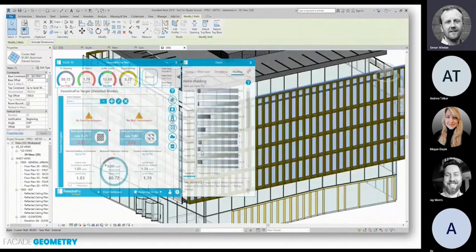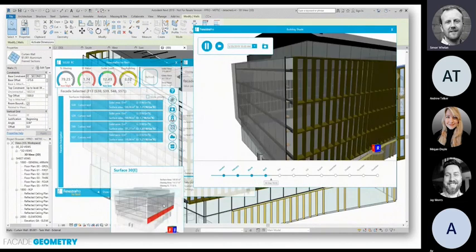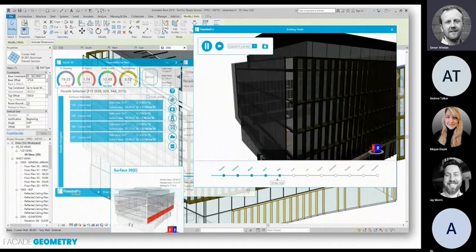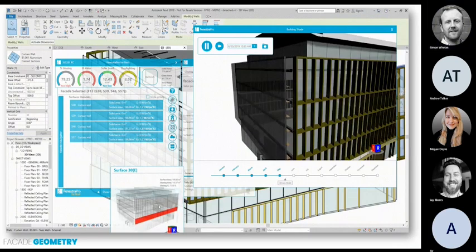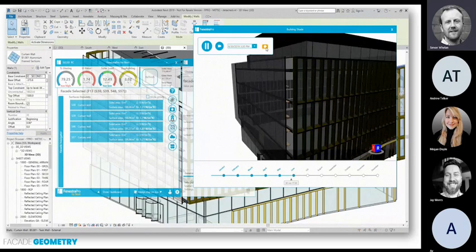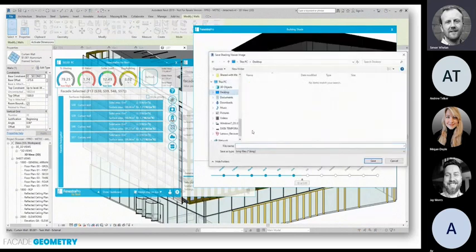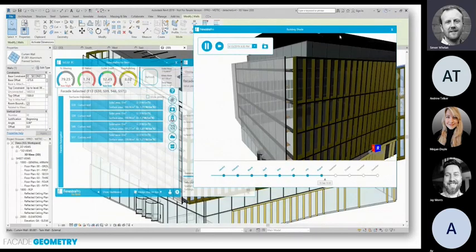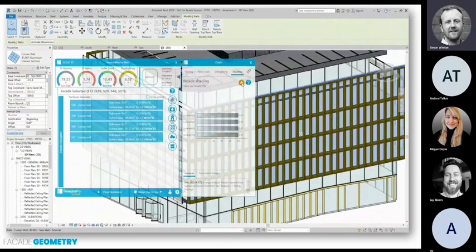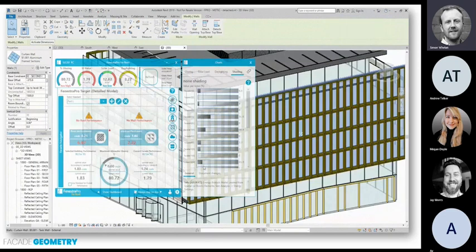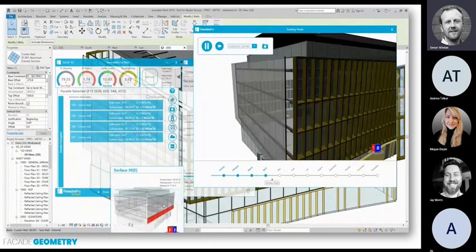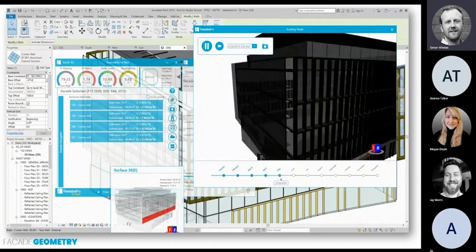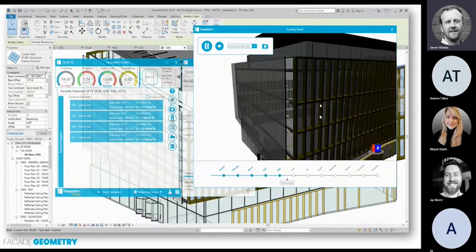But crucially, again, we have the data. So facade 3 to the west is shaded 40% of the year on average. But then looking at it seasonally, January might be shaded 50%, but July is only shaded 25%. So you can, again, just get an understanding of the seasonality of some of your design decisions on these things.